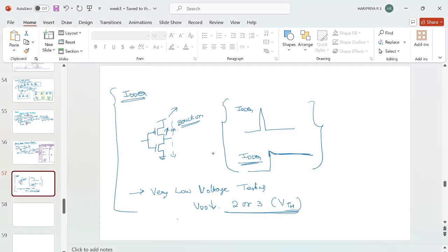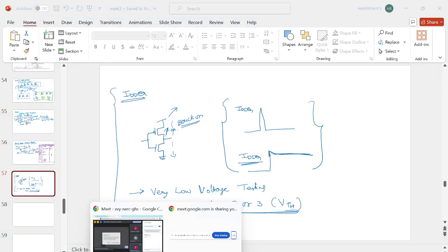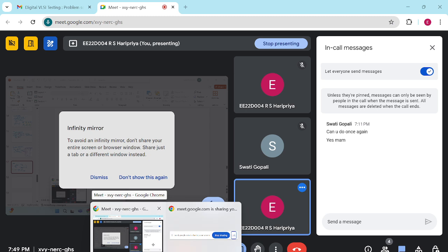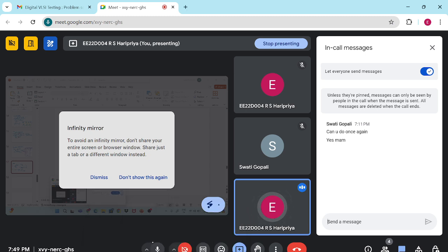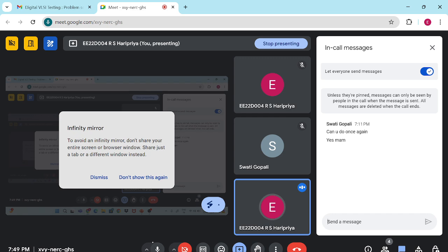And also we have testing with varying temperatures, like low voltage or stress test, stressing it at different temperatures and testing. And for the scan flip-flop, we have already discussed that we use some flush patterns to test it. For whenever we have a sequential element, we use sequential ATPG to generate some patterns and test. And for combinational, it was combinational ATPG. So these were some testing methods.